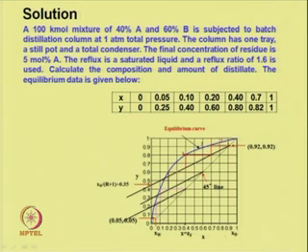Assume the initial x d value is 0.92. We can draw 2 trays, and the composition is given as 0.4. So, for 0.92 as x d we could obtain x w of 0.4. Similarly, at the end, if we plot two stages, 1 and 2, we could obtain 0.05.